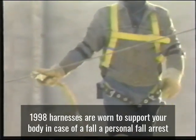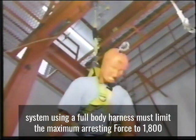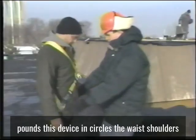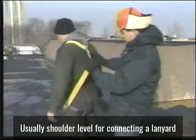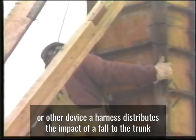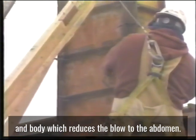Harnesses are worn to support your body in case of a fall. A personal fall arrest system using a full body harness must limit the maximum arresting force to 1,800 pounds. This device encircles the waist, shoulders, and legs and has a D-ring in the center of the back, usually shoulder level, for connecting a lanyard or other device. A harness distributes the impact of a fall to the trunk and body, which reduces the blow to the abdomen.